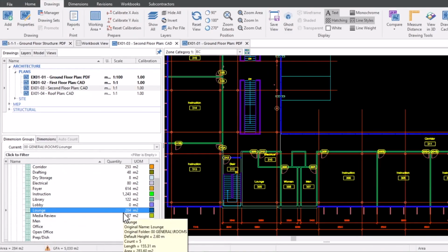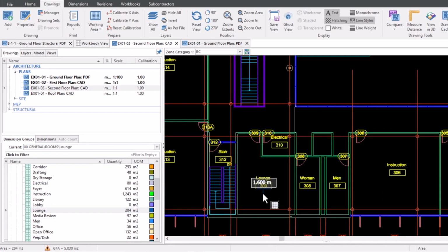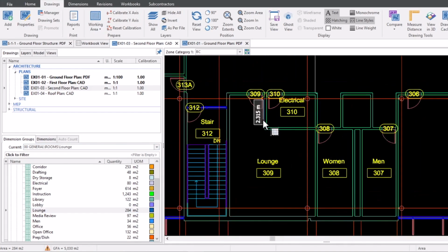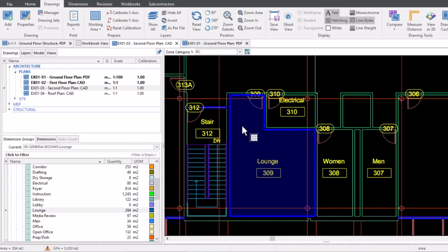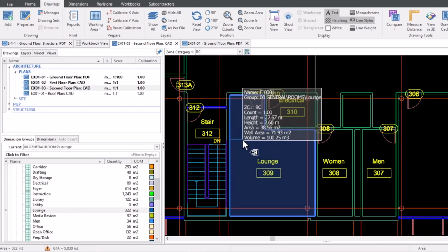So as before, DWG files can be very rich in intelligent content. With a DWG, designers may include continuous lines known as polylines around enclosed areas on the drawing. This means we can use that polyline information to highlight that area by holding down the L key, and with a click of a button, measure the enclosed area.